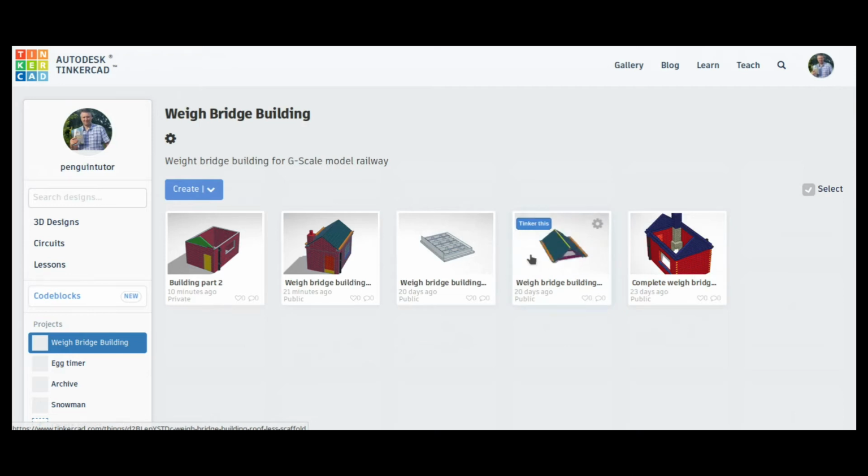The roof is a little bit more challenging to 3D print. When I did the body, the main bit, I used scaffold, and it puts scaffolding inside the window and also on the edges, because I've made the top row of the bricks overhang a little bit, and so that was quite easily removed. On the roof, then, if you're going to print it like this, there's going to be an awful lot of scaffold used.